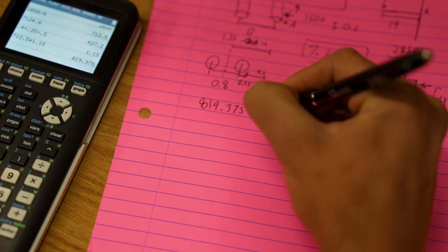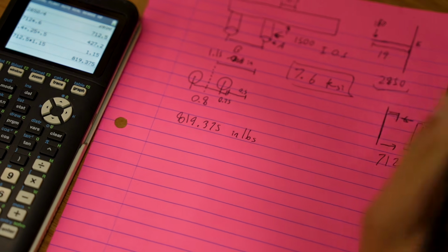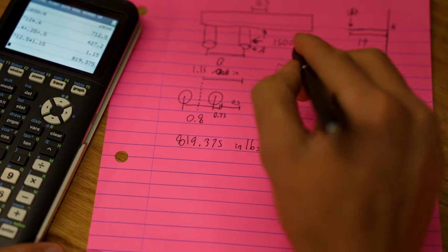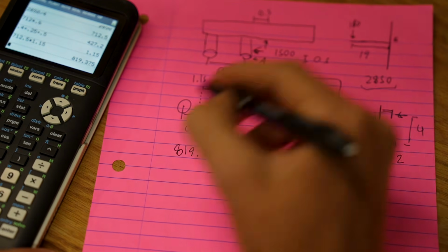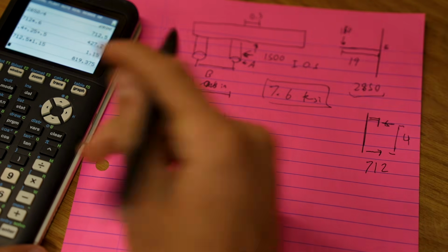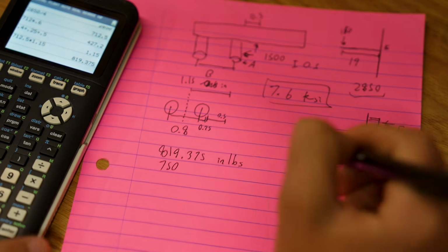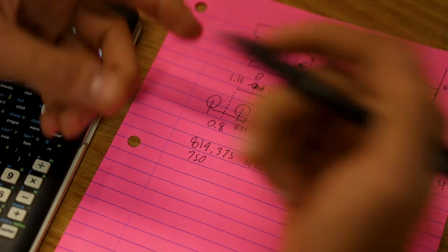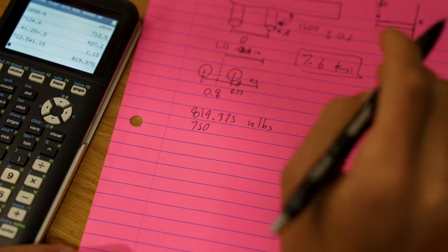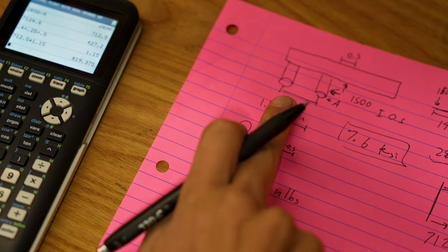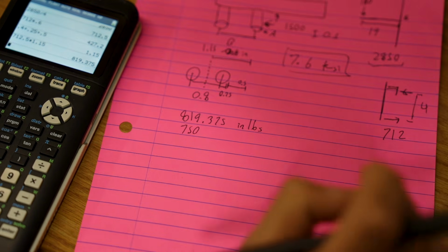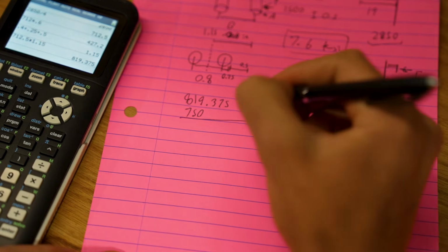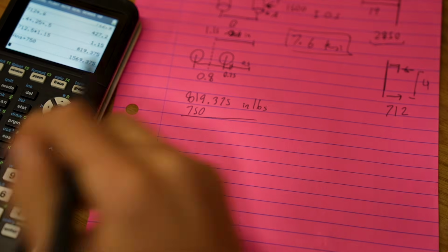819.375 inch-pounds of torque from this one, and then we're going to add that to the other one because both of them act to torque against the structure. So it's going to be that plus 1,500 times 0.5, which is 750. So we're getting kind of equal components of bending from bending away from it as resisting, which is going to add up. But since we're resisting bending across this entire structure, I think we're going to find we're in a much better place.